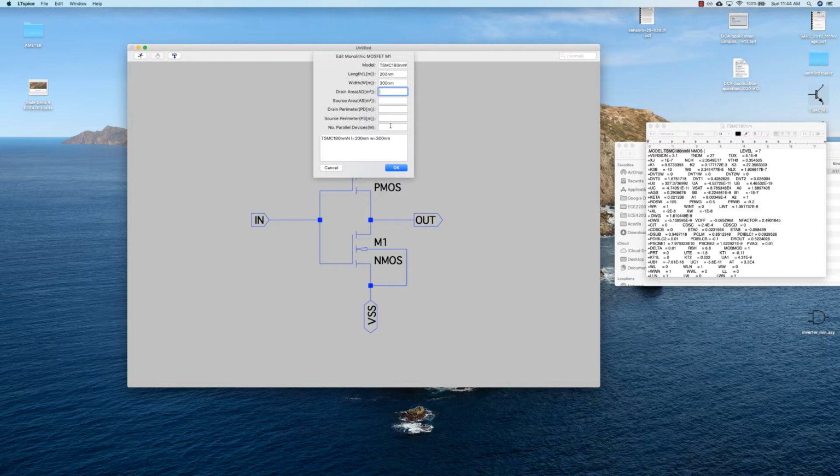Because we're going to be changing these, this is one of those sizing things where you're sizing up and putting different layers of these devices. So we need to parameterize the number of devices, so it'll allow us to do that easily later. I'm going to use squiggly brackets, which means you can do a parametric.